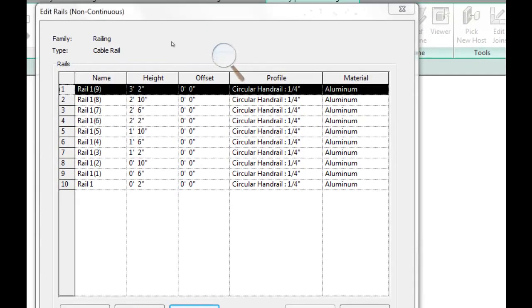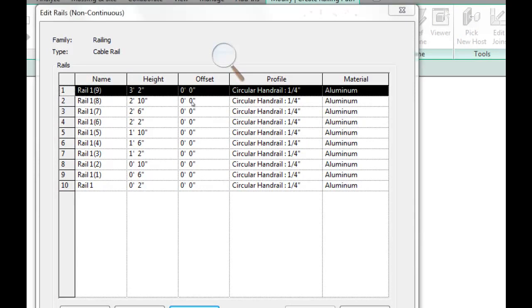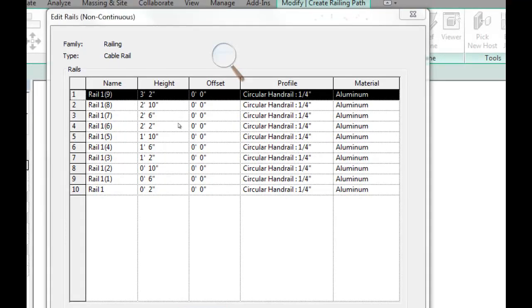So one of the disadvantages of this is, unlike the curtain wall, where I could just specify, hey, repeat this every 4 inches, and it would do it as long as we specify the overall height. It would just repeat this horizontal element every 4 inches. In this case, for some reason, even though you can do that with the baluster placement, for placing railings, it's more specific, and you have to kind of enter in each element line by line. It does give you a lot more pattern possibilities again, so you could imagine specifying different profiles to occur at different sections and so on.